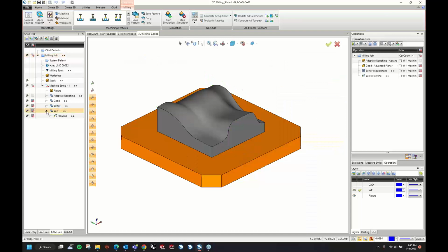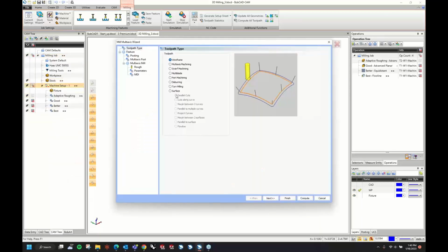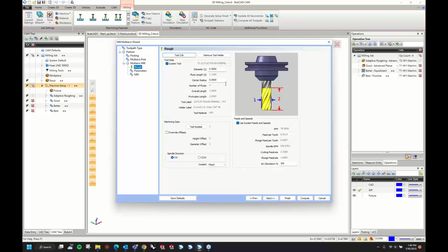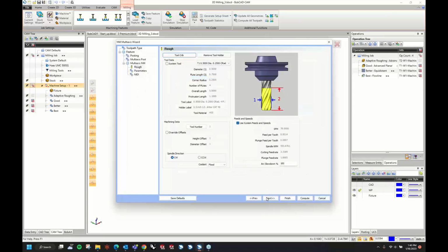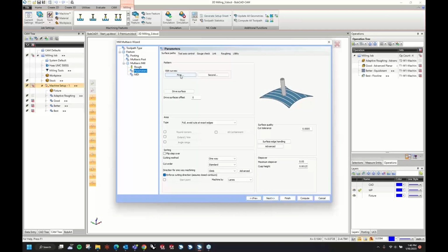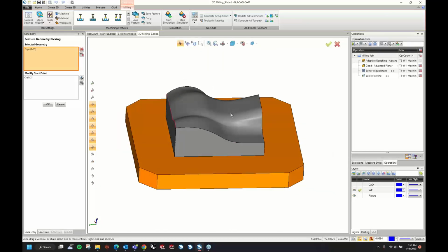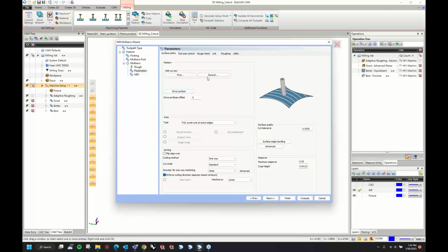But the one I would probably use, and a lot of you may guess this, is going to be morph between two surfaces, or morph between two curves. Either which one, they're kind of the same thing. And the reason I like this one, go ahead and grab our 1/2-inch ball that they're using for this. So again, we'll pick our first and second edge, but the neat thing is I could always change the direction. If I wanted to go across instead of down,